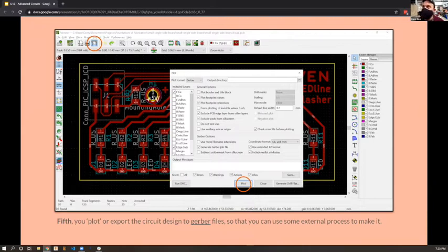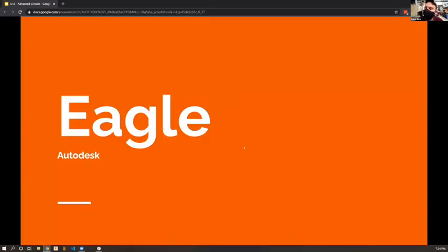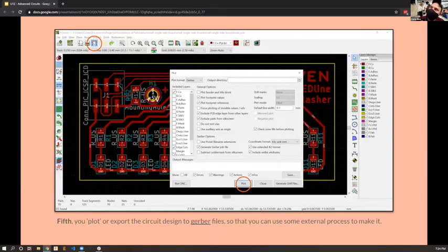And as an artifact of that, they still call taking this geometry and exporting it plotting it, because it was for old designs on plotter machines that would move a pen around and plot out where to draw, or in this case, where to cut or where to print. And so in order to export, you'd use this weird, large format printer looking button, because that's what they originally were designing for. And you'd plot out these models into Gerber files. It's a tricky thing. But from there, you get Gerber file designs. And so they're called Gerber files. And from there, we'll be able to see what you can do with them.